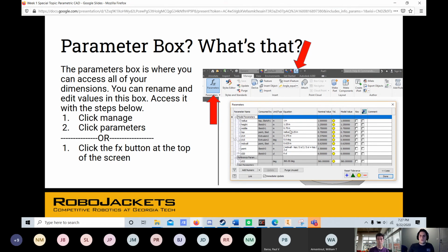The other thing that you can do, which is not something that I've personally done, but other people on my team have done, is set up Inventor so that you can put everything into an Excel spreadsheet and then link it to a system of parts or some assembly that you're using to reference that off of. It's really nice because then you can keep everything in one little file, change things from there, and then update. Okay.